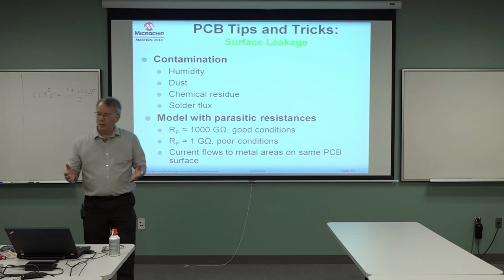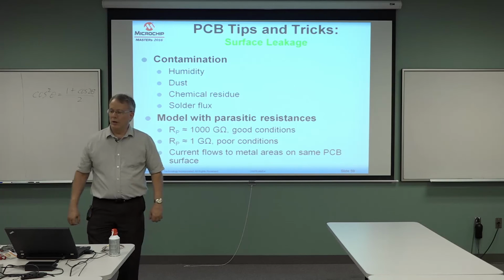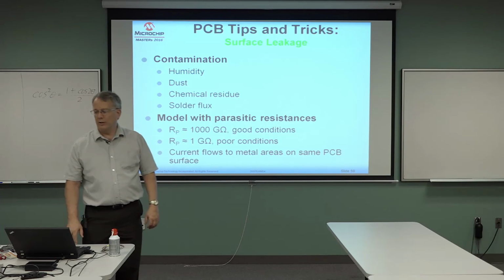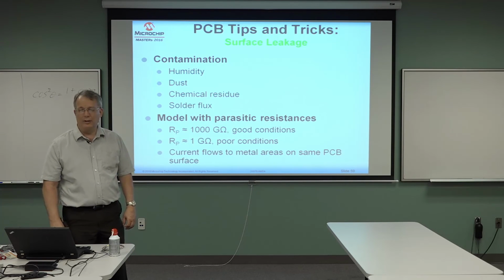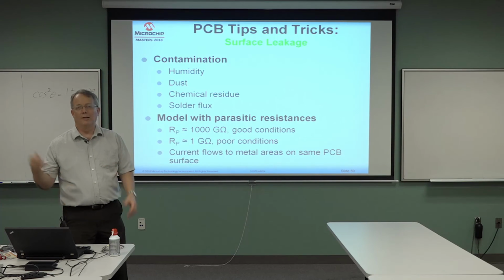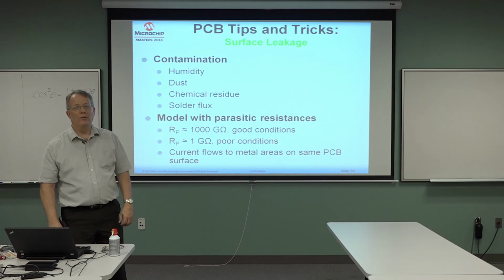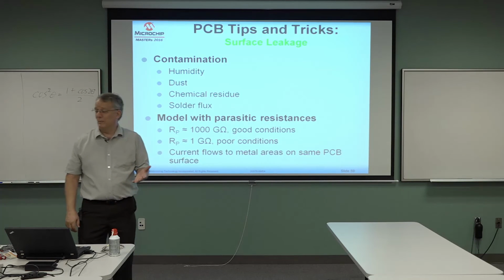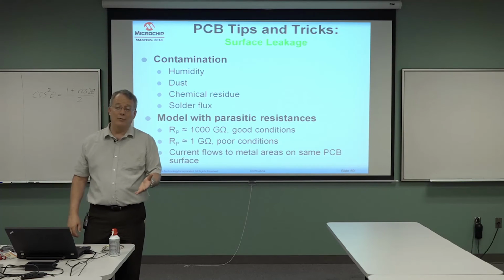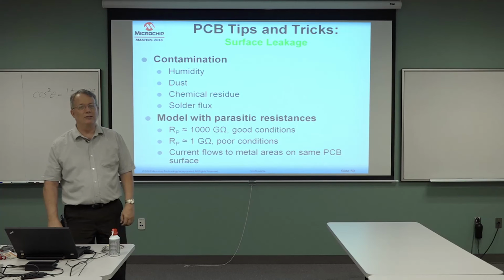So I started way back when as an electronics technician, and I learned early on the first thing you do when you open up a piece of equipment that you want to repair is you get out this vacuum cleaner, by the way, not your wife's vacuum cleaner. You get out a vacuum cleaner and you carefully vacuum out all the dust. And that clears up a fair number of problems, and at the same time, it makes it easier for you to find everything that's going on. You can see better.